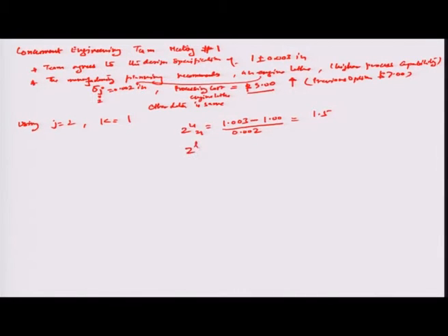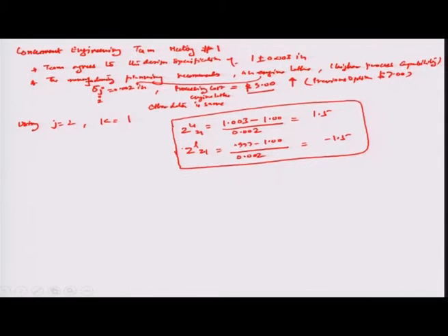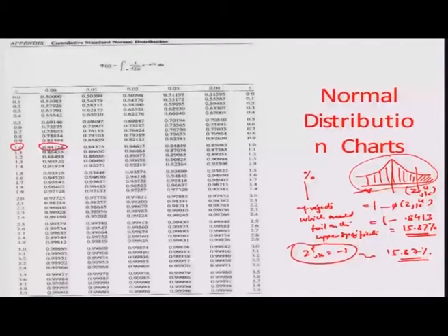Okay, and then the ZL21, using the engine lathe over the specification 1, is exactly 0.997 minus 1.00 divided by 0.002, that is actually equal to minus 1.5. Okay, so that is how you have the upper and the lower specification limits set in. So, if I look at the 1.5 number in the normal distribution table,